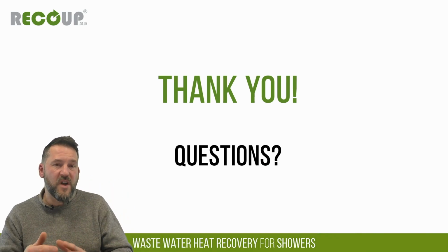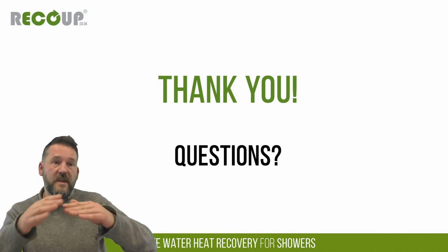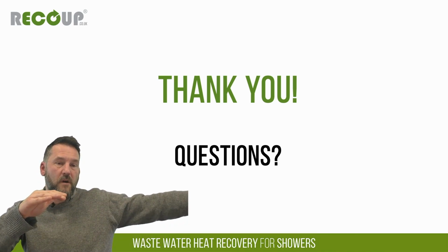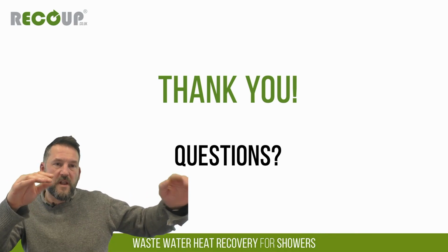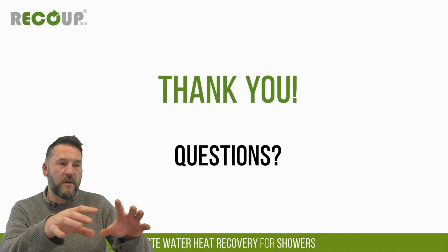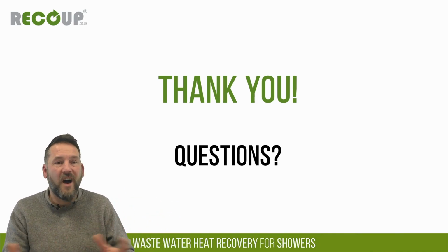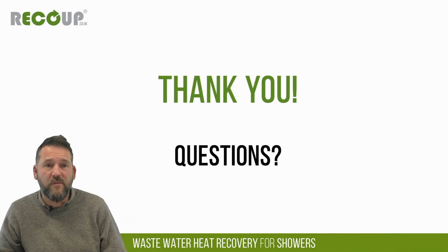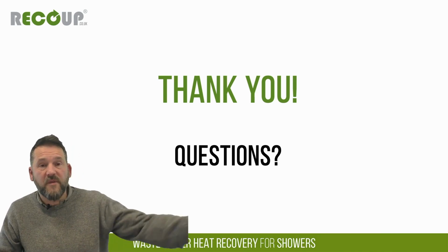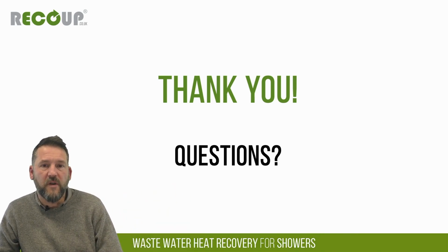So anywhere between 95 and 105 millimeters would be standard clearance. Obviously, if your pipe runs are running further off, you may need to adjust that slightly. But in most cases, the SVP or the drain is very localized to the bath, so in most cases, 105mm would be pretty standard. We have a demonstration unit here, so we can show you how that works on a direct call.